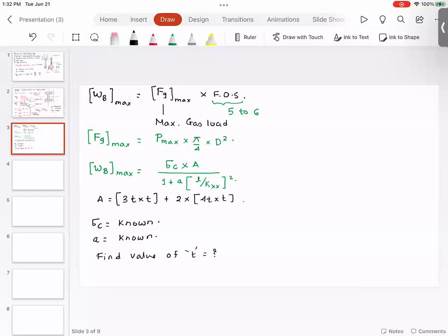So as far as the engineers are concerned, once we understand this is how our design is going to look like, this is the material that we want, these are the dimensions that we want, then we go and get the catalog items. Many a times those catalog items will be slightly off dimensions, then we have two choices. Either we modify the design so that that catalog item can fit, as a drop-in replacement, or we will try for some minimal machining on that off-the-shelf part that would reduce the cost of the overall product.